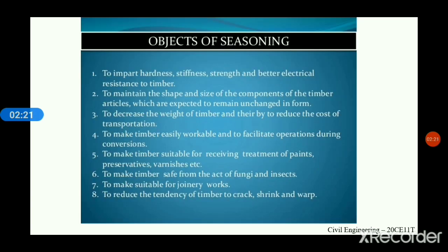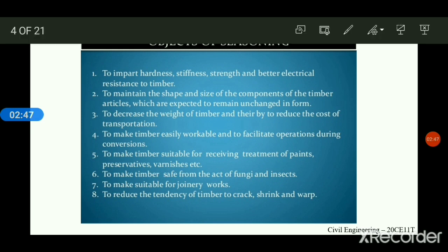Some of the objects are there for why seasoning has to be done. We'll discuss what the objects of seasoning are. Generally, seasoning is done to give hardness, strength, stiffness, and also electrical resistance to timber. It will maintain the shape and size of the timber, which remain unchanged.